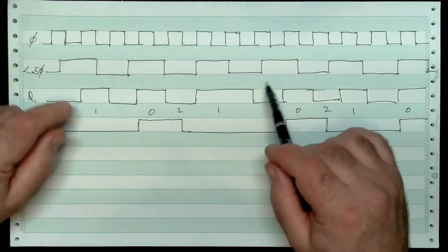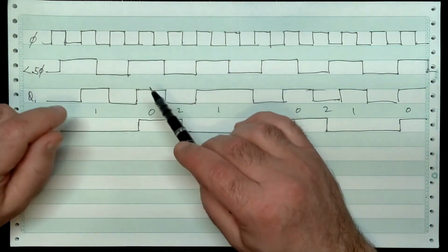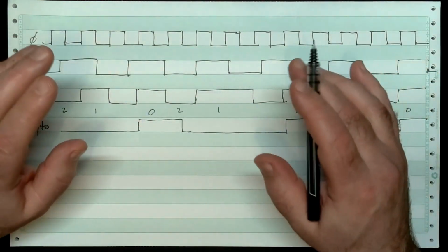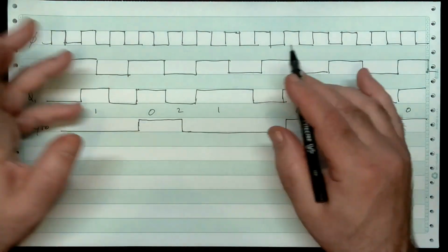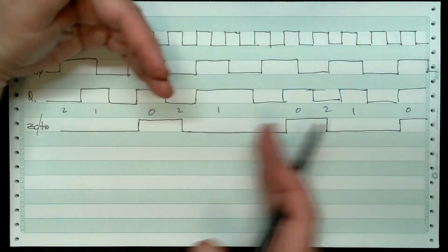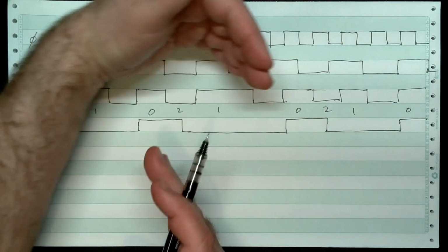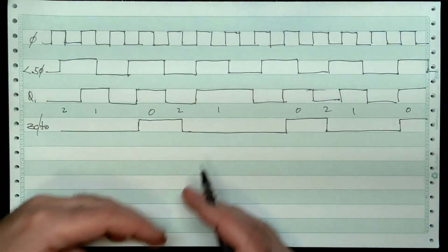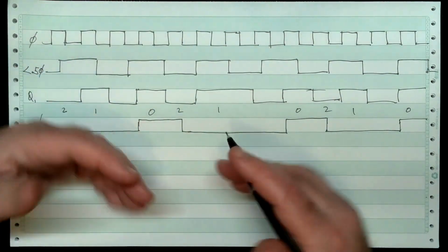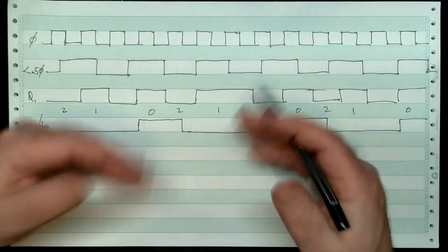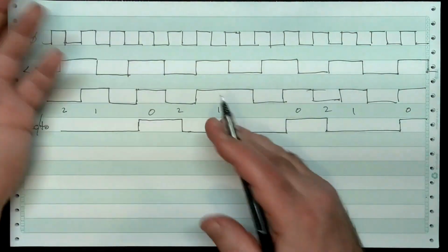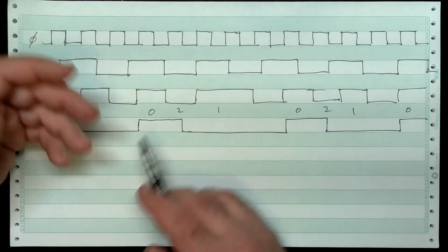Even if I bought 2 10 megahertz oscillators with the highest precision, best money can buy, they won't run at the same speed. They'll have a tendency to speed up and slow down a little bit over time with temperature and everything else. They won't run at a constant speed. They won't even run at 10 megahertz. One might be faster, one might be slower, and the same thing would ultimately happen.